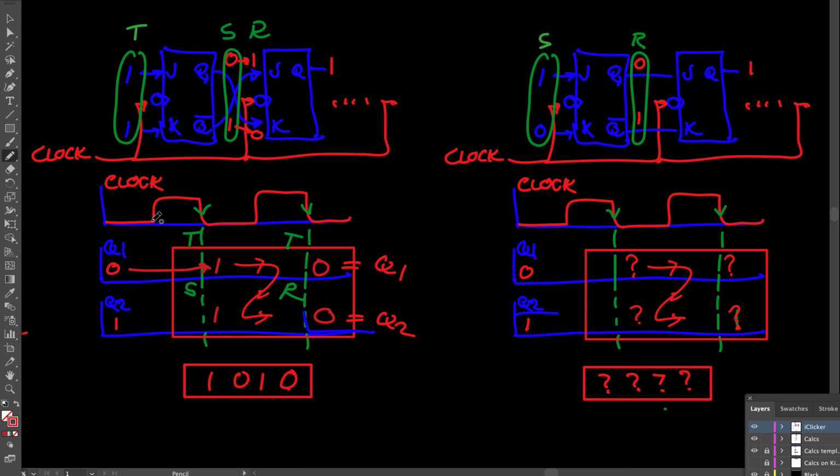What we looked at is applying two clock pulses to these two JK flip-flops. And since they're negative edge triggered, we expect them to change on the negative edges as shown by these dotted green lines. The first flip-flop was configured into toggle mode, so therefore this chart is for toggle. For the first flip-flop, toggle once here, toggle a second time here corresponding to second flip-flop. The data came in as a 0, it toggled to a 1, and then came out as a 0 after